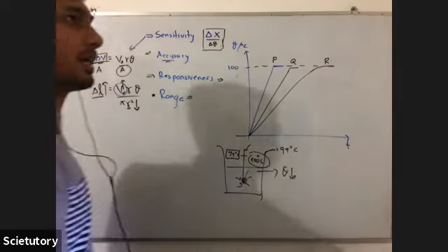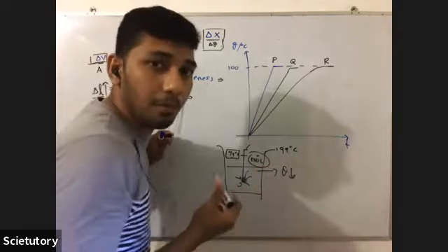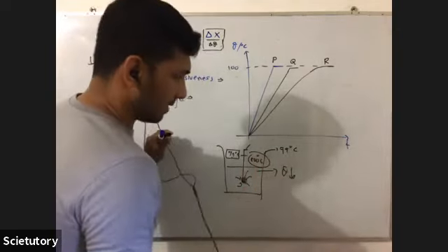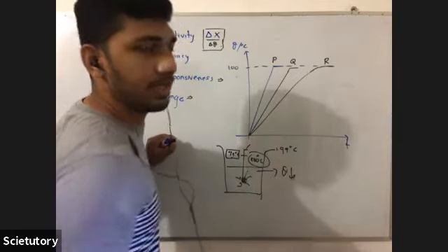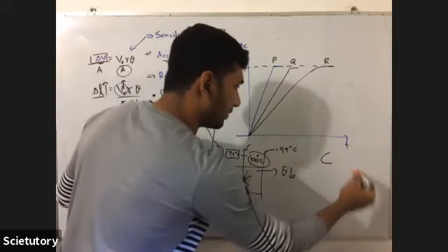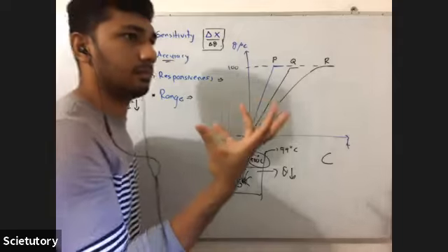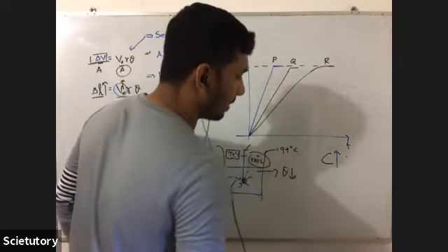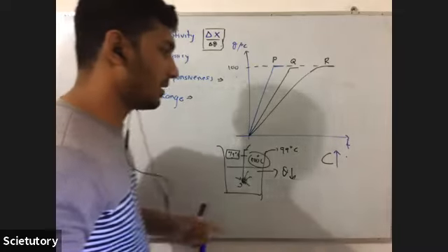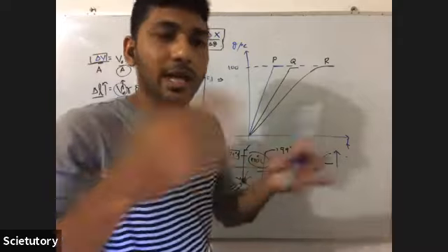So what factor determines the accuracy? That is the amount of heat absorbed from the system by the thermometer. So the factor that determines the accuracy is the heat capacity of the thermometer. So if the thermometer mercury and the glass has high effective heat capacities, they need higher heat to expand.